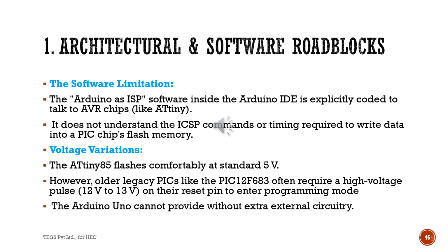Architectural and software roadblocks. The software limitation. The Arduino IDE's ArduinoISP software is explicitly coded to talk to AVR chips. It does not understand the ICSP commands or timing required to write data into the PIC chip flash memory.